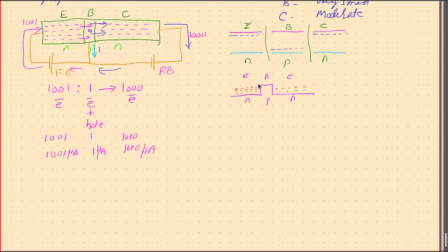But if you enlarge this, there is a gap between the highest energy any electron is possessing at a given time and the minimum energy required to get into the base, that is the energy gap we had. This is the minimum energy we need to supply, and to make sure that these electrons cross the junction, this gets forward biased.